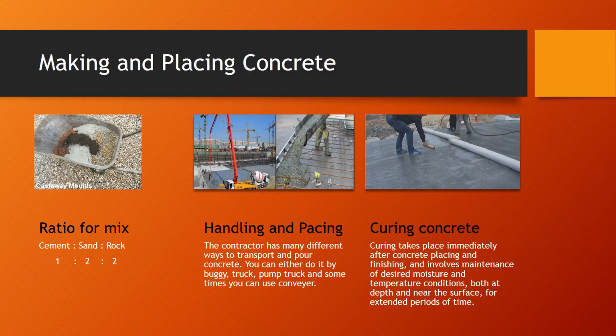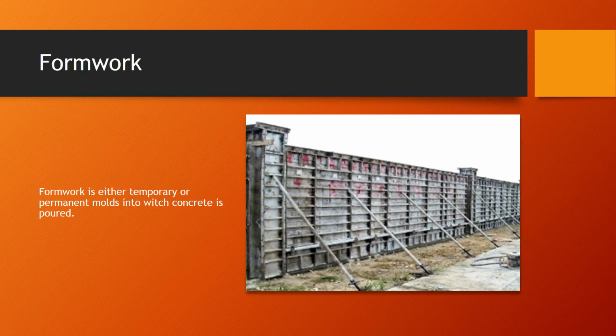Curing concrete. Curing takes place immediately after concrete placing and finishing, and involves maintenance of desired moisture and temperature conditions, both at depth and near the surface, for extended periods of time. Formwork. Formwork is either temporary or permanent molds into which concrete is poured.